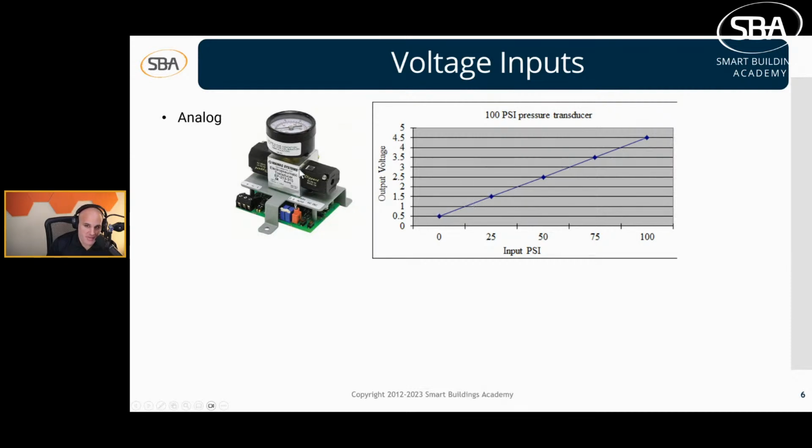There's a little valve in here that would regulate the control pneumatic air, because there's main and then there's control. Main is your high pressure, and control is typically your 0 to 15, 0 to 20 psi.